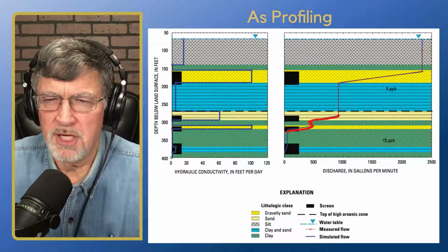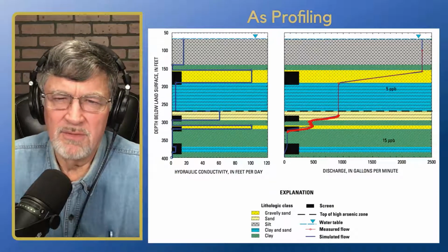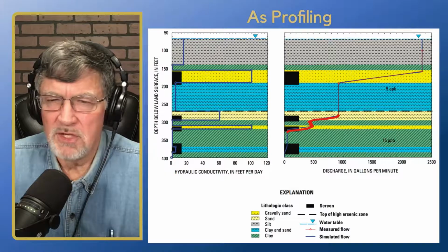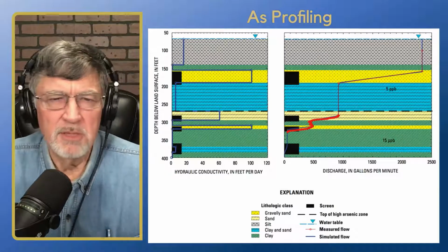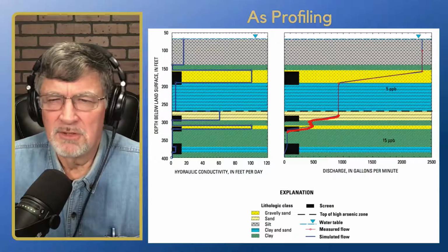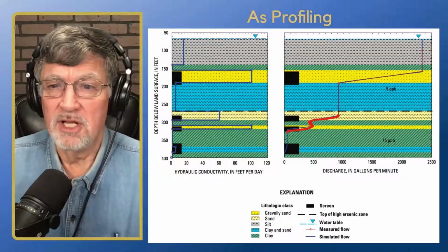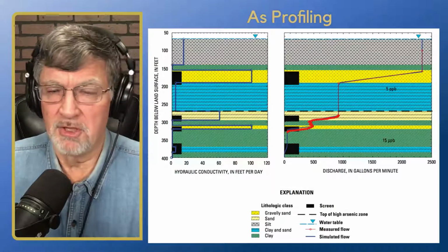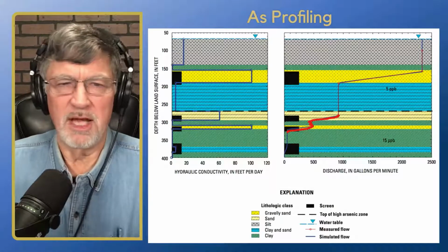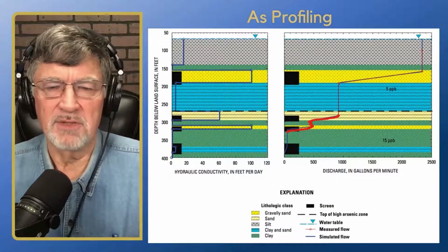but there's very little flow down below in that lower zone where it's screened. So we would probably want to take those upper screen zones that are plotted there and seal off the bottom one, and you're likely going to be below the MCL for arsenic. In this particular case, you might have diluted things out enough with the flow from up above, because you really don't have much of the high arsenic flow coming into the well. But just to be safe, I would design this well so that we didn't take that lower zone at all and we didn't have to mess with that. And then we stay well below the MCL for arsenic. So that's an example there.